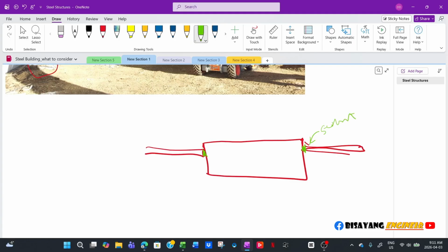So we'll just seal this part here, and then expansion joint material, it's like a rubber, like an asphalt-impregnated membrane, and then with sealant on top. Usually we have a half inch gap, so that if this one vibrates and this will move a little, it will not create a force transfer to your slab and eventually lead to cracking of your slab. So you have to have a gap here.